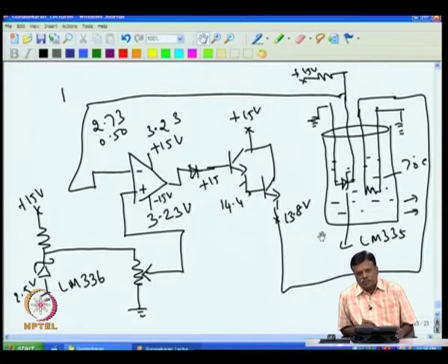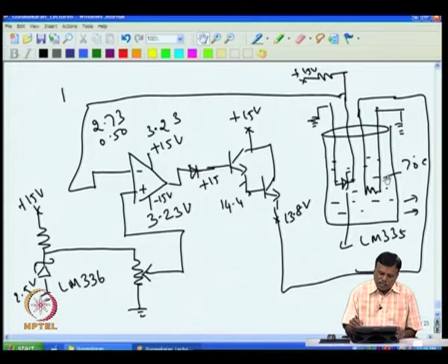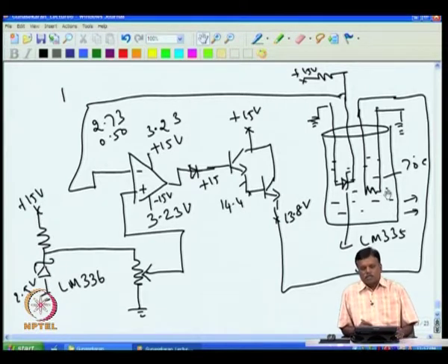In fact, most of them, even today, it is used. It is very easy to construct, but the only problem is that if you want 70 degree, it will be going up and down around 70. Once switched on, it will go a little above 70, and then slowly it will come down, then come to 69. So, depending on the system, there will be overshoot and undershoot. If the system is fast, the overshoot and undershoot will be small, otherwise they will be more. Other than that, it is a good and famous controller, an age old controller, and works beautifully, there is no problem, except that you have a small temperature fluctuation.